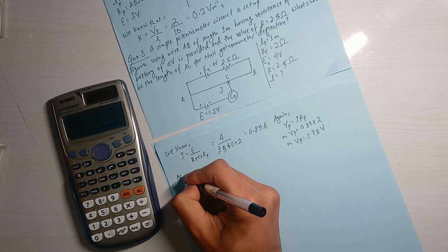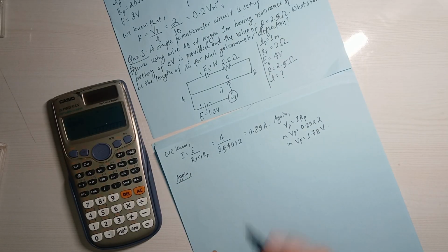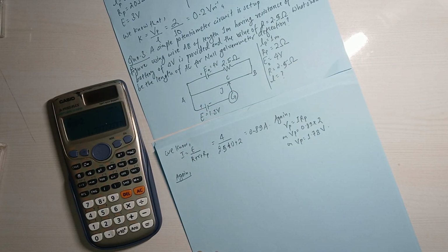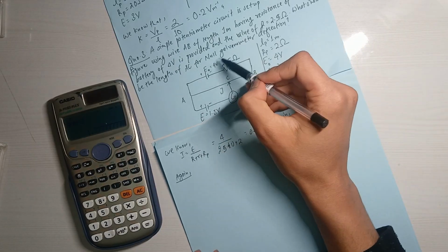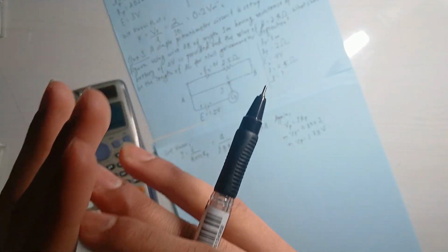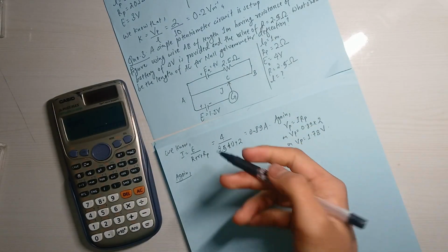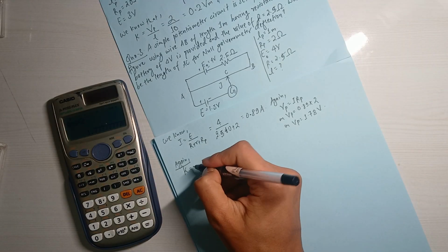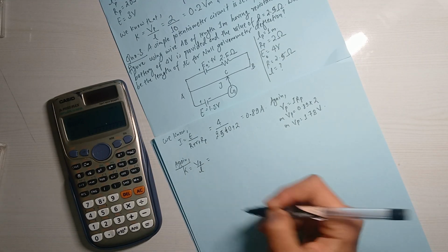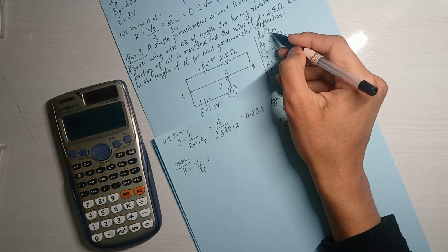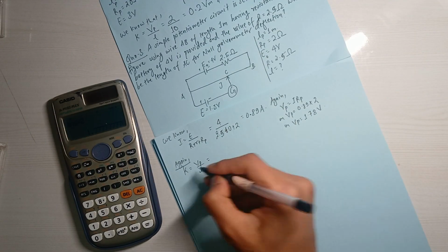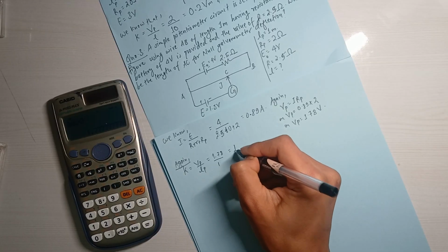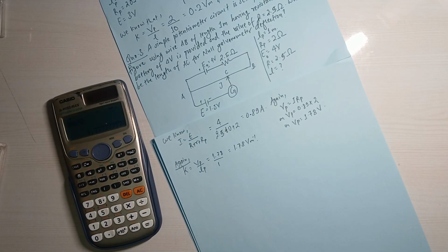And again, now we are asked to find the equivalent point, and we need the length. So for the null deflection, that means it is an equivalent point, and that is an application of potentiometer. As you can remember, the law of potentiometer says that E equal to KL. So we need K to find the L. So K, the potential gradient, will be equal to the voltage per unit length. So Lp, we need that. The length of potentiometer is 1 meter, that's given. So Vp we found out is 1.78, by 1 will be the same, 1.78 volt per meter. That is the potential gradient.